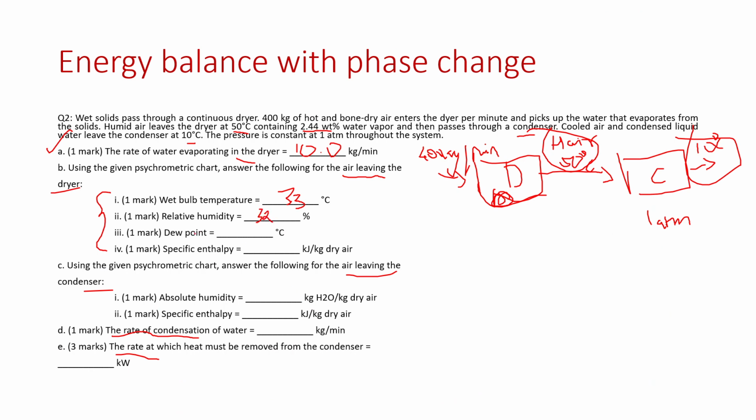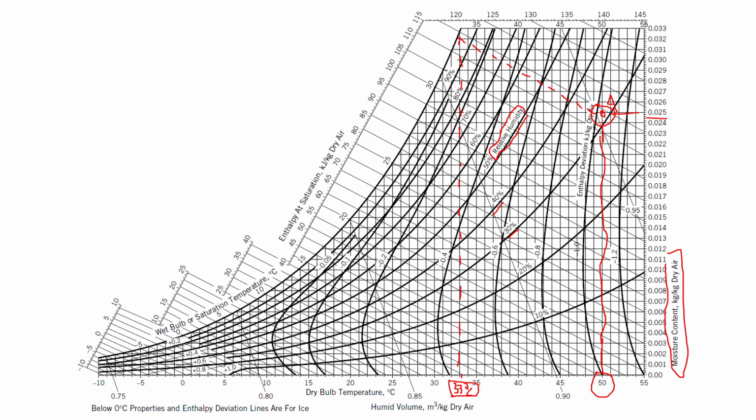Next is the dew point. Dew point is the point where the air begins to condense. So the dew point we will find out by drawing a horizontal line from the point A, along this line, which I am denoting in dashed lines, which comes somewhere here, and extending this downwards. Or we can find it with the scale that is given in the slanted axis itself. 27, 28, 29, 30. So if this is 29, this will be, if this is 28, this will be 28.5. So when we extend this downwards also, we will get the same value, which is around here, and that is 28.5. So this will be the dew point.